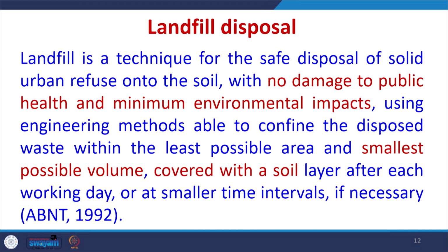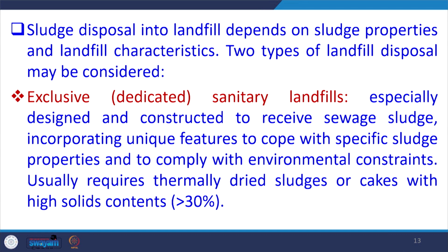Now, landfill is a technique for safe disposal of solid urban refuse into soil with no damage to public health and minimum environmental impact, using engineering methods which are able to confine the disposed waste to the least possible area and smallest possible volume, covered with a soil layer after each working day or at smaller time intervals as necessary. So, sludge disposal into landfill depends upon the sludge properties as well as the landfill characteristics. So, the disposal will depend upon both.